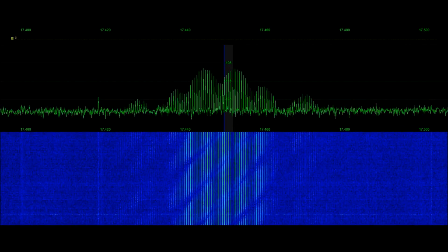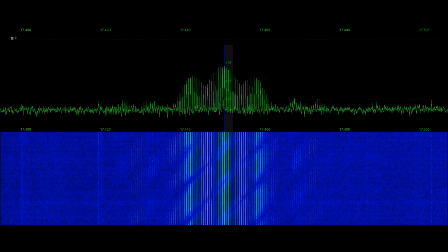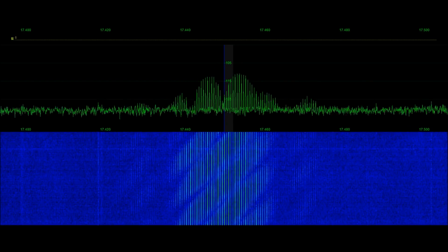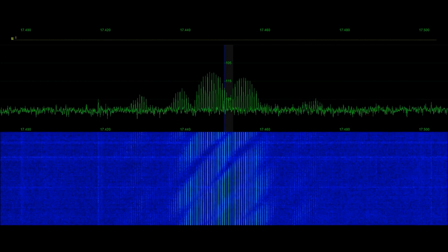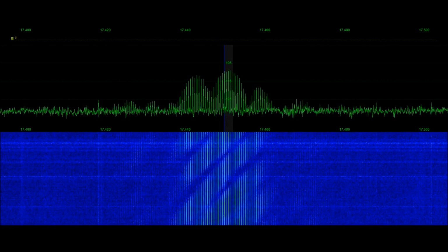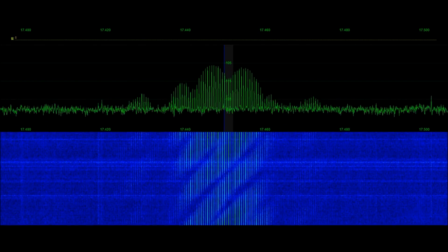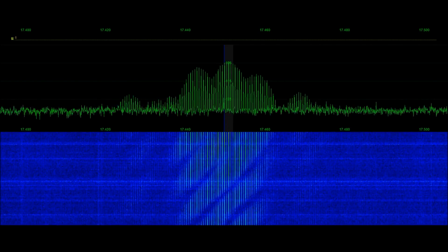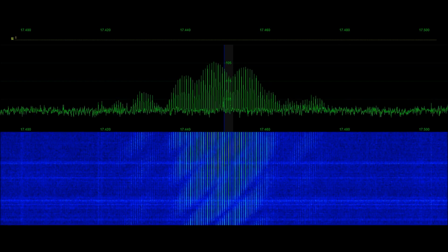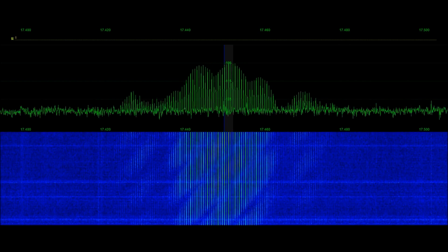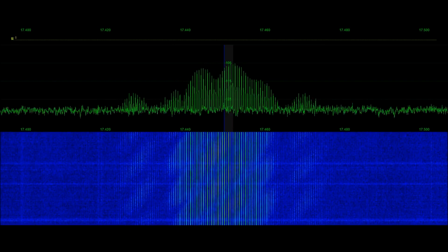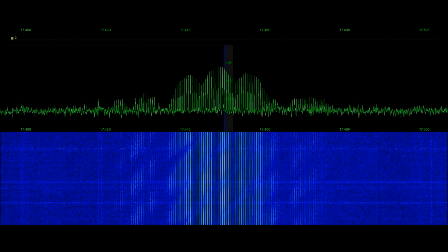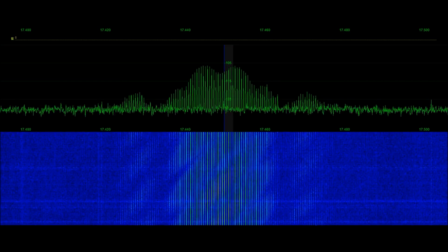As referenced so far, we've left the receiver in an upper sideband position, listening about 2300 cycles. So any audio that you may have heard so far is actually a product of the beat frequency oscillation of the receiver, as it is taking those individual frequencies and then remodulating them and giving us that audio component. And that's important to note because there really is no audio on these particular signatures.